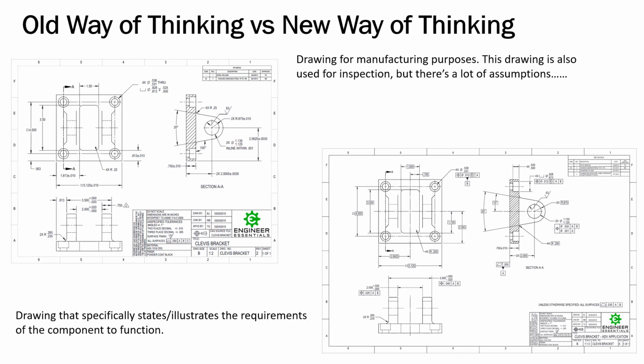So consider this though for manufacturing. And this is really a question for you, Jamie. Would it be the GD&T on the print that could make something impossible to make, or simply the tolerancing? So in GD&T, we're supposed to make tolerances looser, not tighter. GD&T is not supposed to be complex. It's supposed to be simple to understand.